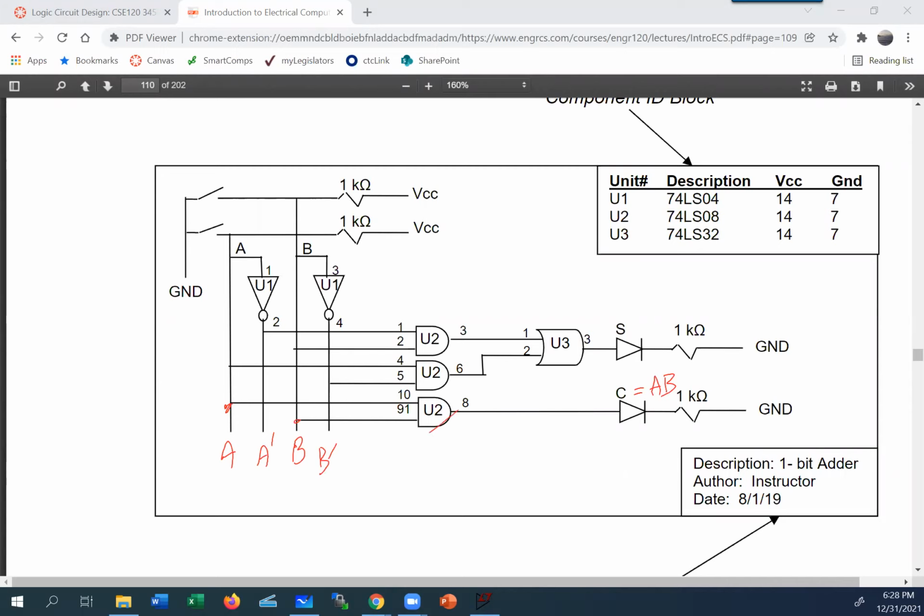And it looks to me like we are using pin 9, looks like 9-1. I don't know why it says 9-1, but anyway, pin 9 and pin 10 of this. So how do I know this? I went to the data sheet and looked at it. And why am I using pin 10? Because 1 and 2, this is the first, I used it for that. The second one I used for the other one. And the third one I've left for this. And then there's yet another one available as well if I need it.